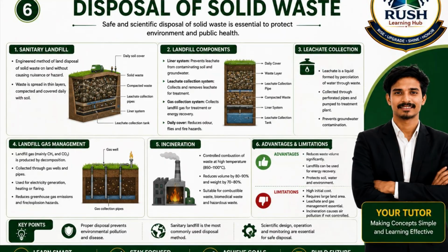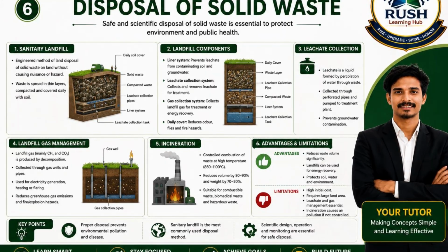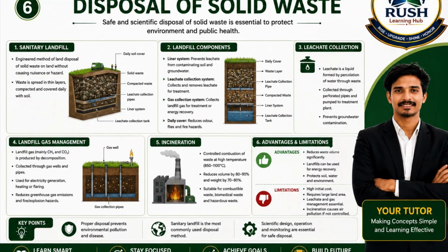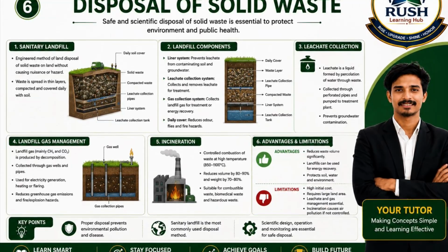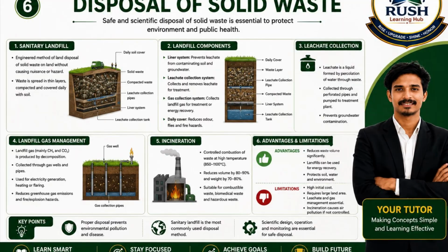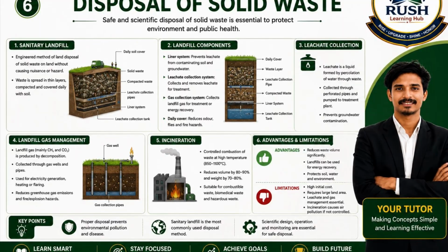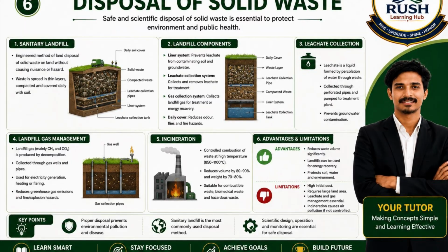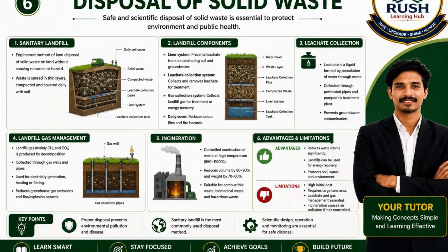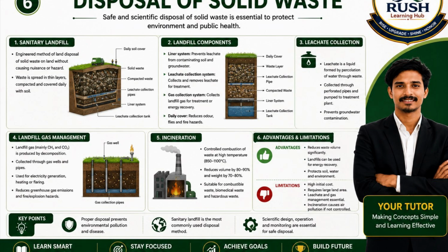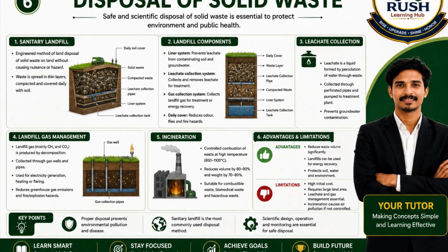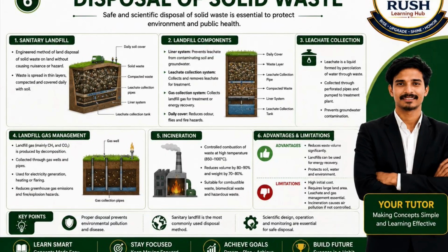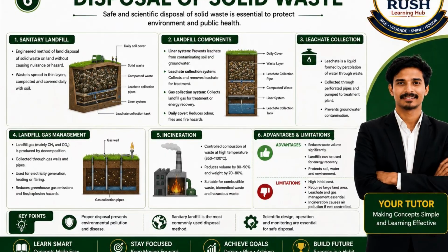Now let us understand the important components of a sanitary landfill. The first component is the bottom liner. The bottom liner is usually made of compacted clay and high-density polyethylene, commonly known as HDPE. Its main function is to prevent contaminated liquid from entering the soil and groundwater. For the UGC NET examination, remember this important point. The liner prevents groundwater contamination.